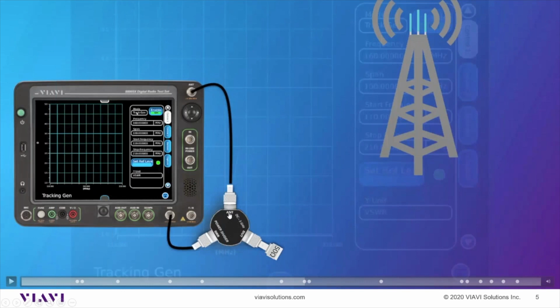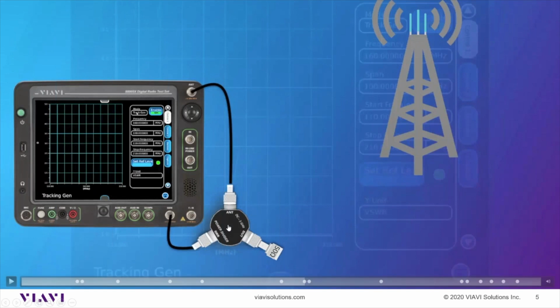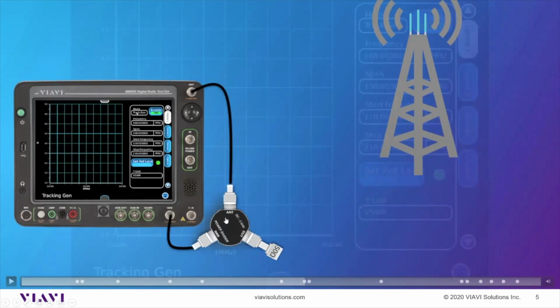I guess I probably ought to mention this. We have one port on both of these that says antenna. And of course, that can be confusing because you're getting ready to test an antenna, so you would think possibly that that's the port that goes out to the antenna. But just remember that we designate that as the device under test port. That is what's going to go out to your antenna or your duplexer or whatever it is that you're testing at that time. And then the other one is the GEN port, designated GEN, and it goes in the GEN port.